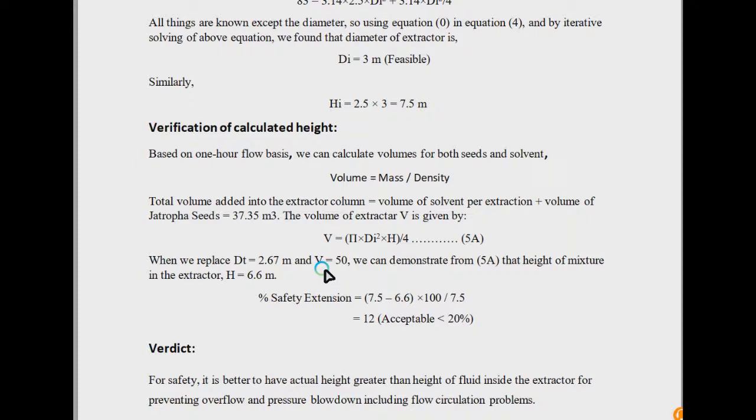That is based on experimental techniques, and most of the time you take it from the literature. But for solvent extractors or systems in which solid slurry mixtures are used, most of the time you do not get enough data, so you can iterate your system and get a reasonable answer. If the time is calculated here, you can calculate the overall volume required based on that time.